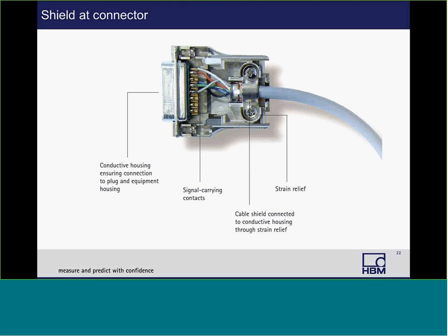So, I'm talking about the requirements for a good connection of our shield. EMC compliant wiring requires that the signal ground and shield be separate. Therefore, the shielding can be connected to earth at several points: to the amplifier housing, to the sensor housing, or other ways.